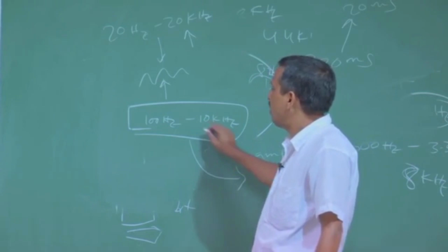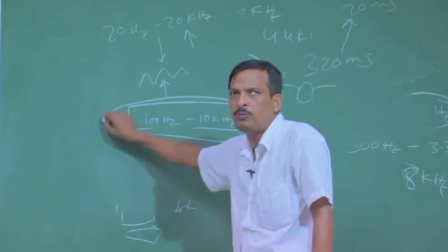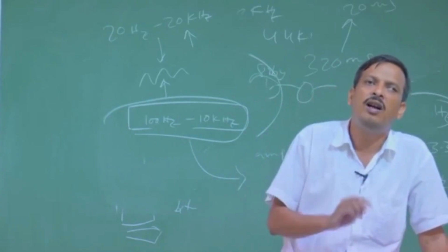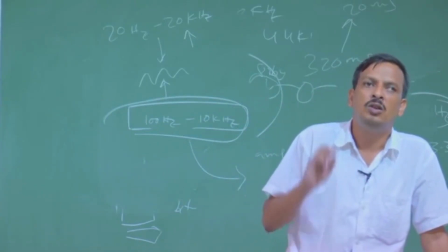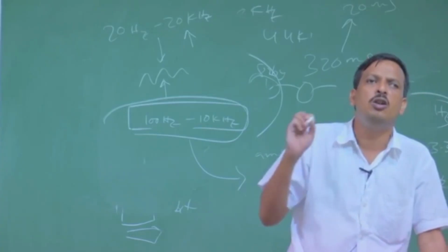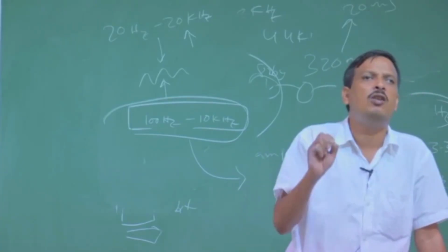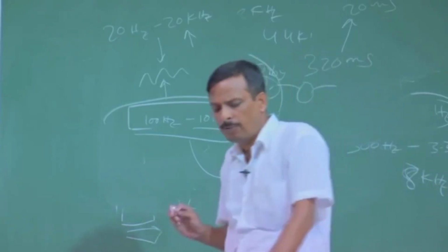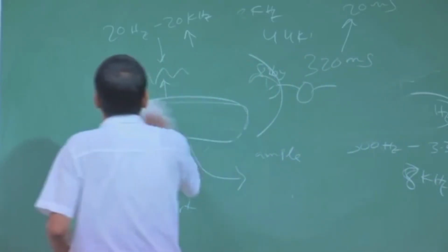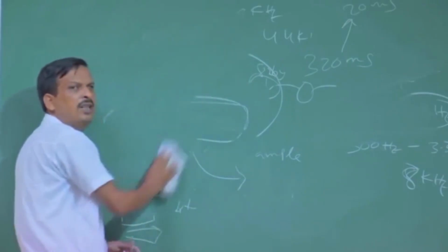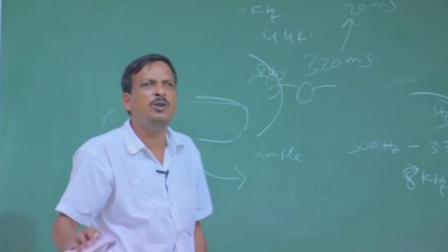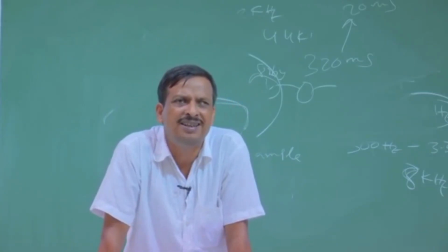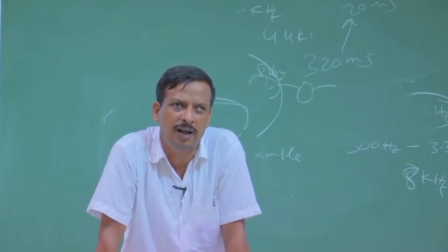Okay. So, selection of the microphone frequency response, microphone type, how to connect it, all are very important. Which microphone I should use depends on what kind of application I want to develop. Suppose I want to develop speech coding for a telephone channel, then I should not use a very high end microphone whose frequency response is 20 kilohertz, because my signal is 4 kilohertz band limited.